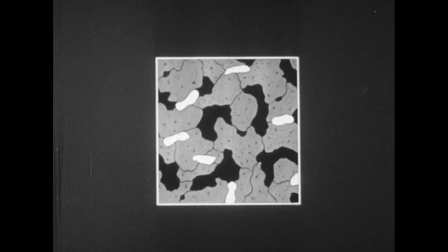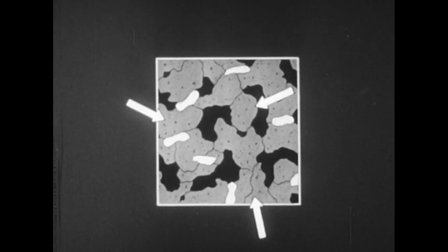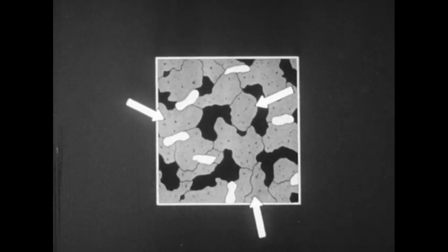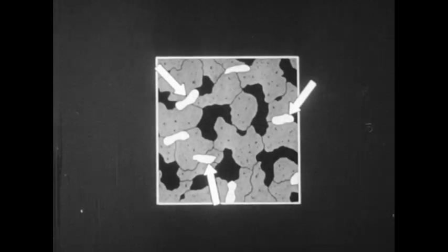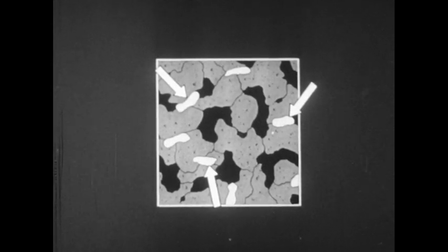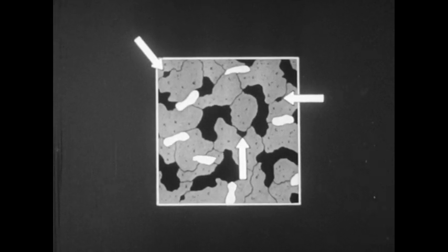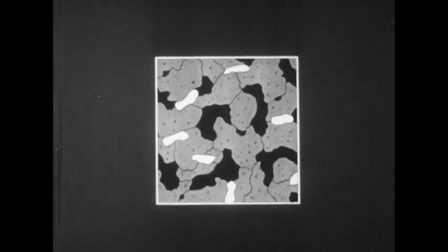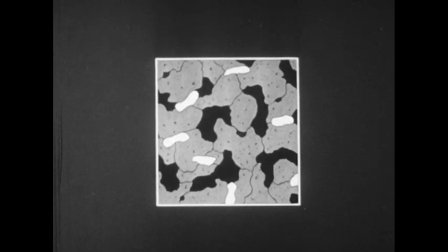Here in this schematic cross-section, greatly enlarged, of part of a briquette before sintering, we see the compacted powders. The dark gray particles are copper. They are in a ratio of about 9:1 to the light gray particles, which are tin. We can see a few small graphite particles, which are black. The other black areas are voids. The stearic acid, present in very small amount, cannot be seen in particle form. It has been smeared in the mixture by the pressing action.